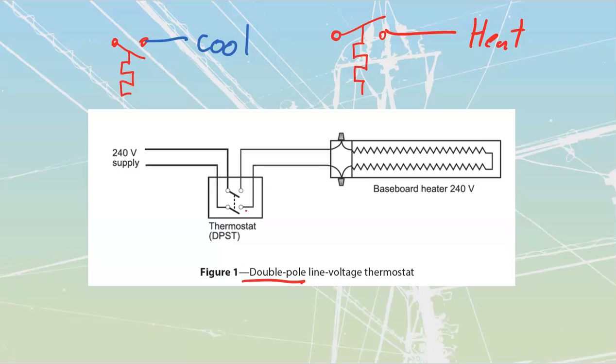Thermostats are going to go and automatically turn on and off our baseboard heater. Usually they're going to involve a little spring-controlled micro switch inside there that's going to be toggled by some other type of element, a bimetallic strip being our most common one that we will utilize on these. If the thermostat breaks both lines for a 240 volt type of system, we are allowed by Canadian Electrical Code to have a marked off position on it. But most of our thermostats that we are going to see out there are not going to have that.